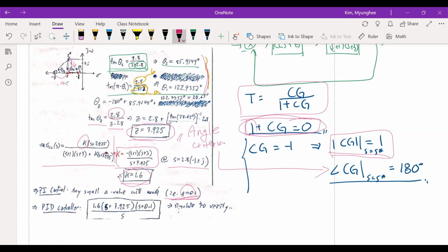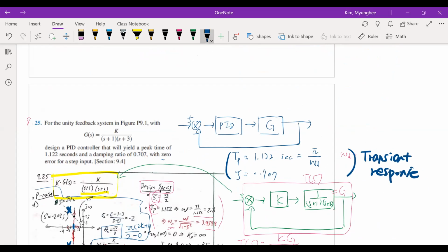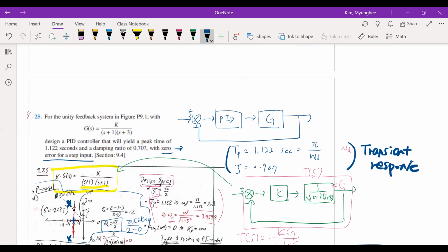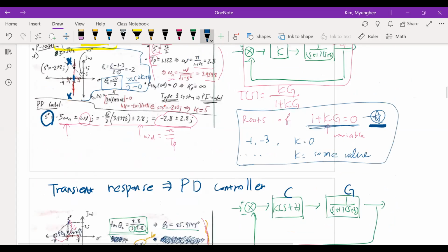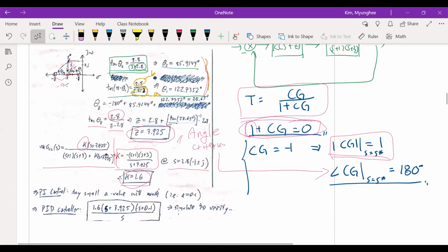Well, before going even there, the other requirement was 0 steady state error. It means that you need an I controller. And then by simply adding I, I can make the root locus a lot different. Now you already found a good pole location, a good controller to meet the transient response. But if you have only an I controller, the PD controller will not work anymore. So instead, you can design a PI controller not to vary your root locus a lot.